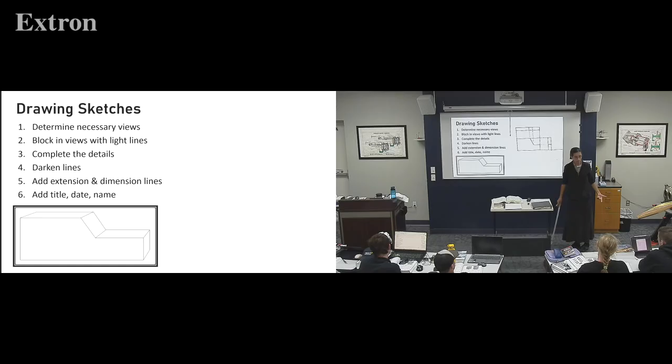So now hopefully it's looking a little more like, alright, we got our front view here, top view there, side view here. So then you'll erase the lines that you don't need. There's extension lines, right, or what do you call them? Not really, because an extension line would be for measurement, like the break and extending out. So these are just kind of helpful guide lines. Oops, I erased a little too much there. That one should have been dotted there.